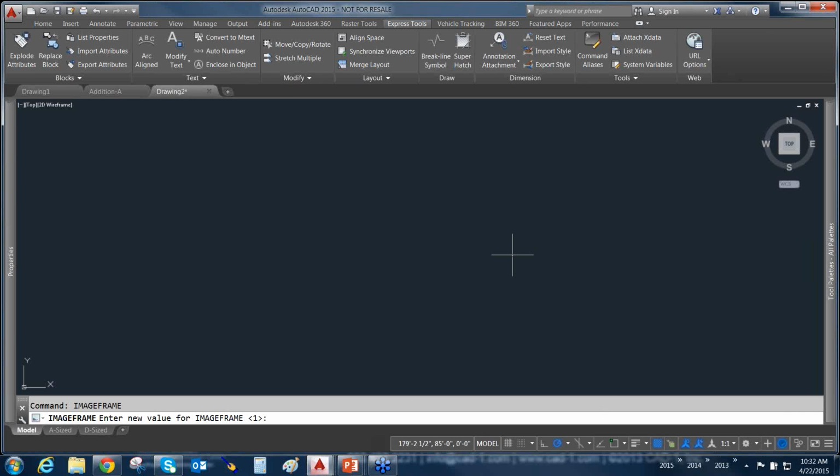If a template is modified, would the users be notified? And if not, is it possible to import the changes painlessly? No. No to both. That's an easy question. Okay, so if the template's modified, first question, would the users be notified? Here's the problem: when you use a template, it makes a static copy of the original template. When I hit new, it made a static copy of my current template, and it created a brand new drawing for me. If somebody gets back in there and makes changes to the template, I won't see those changes. I'll have to do that manually inside my current drawing.